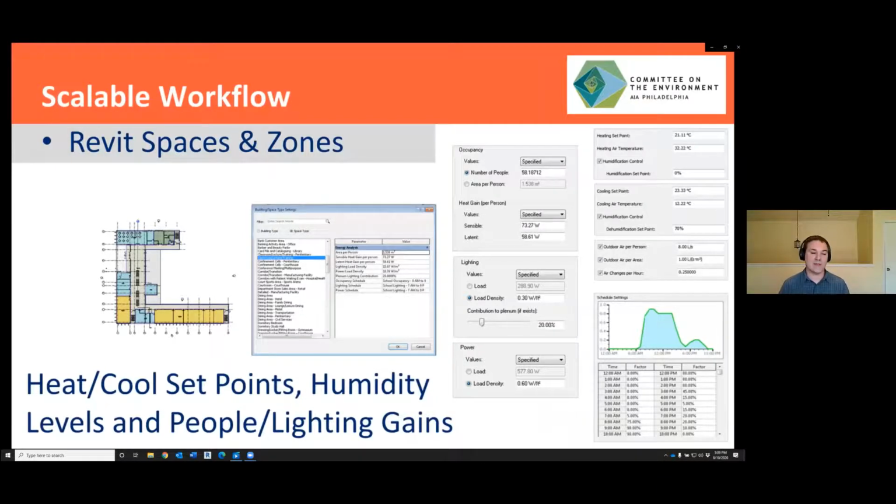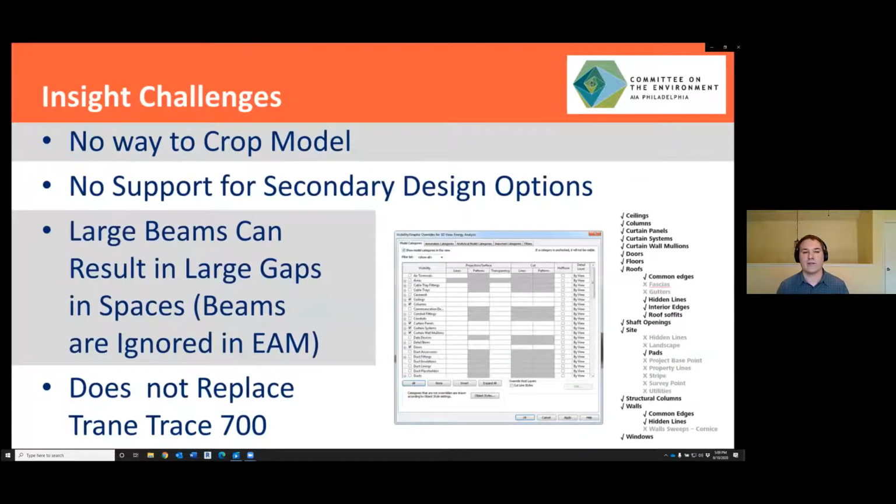This gets really complicated, but if you start to use spaces and HVAC zones in a detailed Revit model, you can set heating and cooling set points and even power for specific electric loads. However, based on the occupant type in a multi-story building, you're automatically going to have an elevator load showing up in your design, but you can account for other loads.